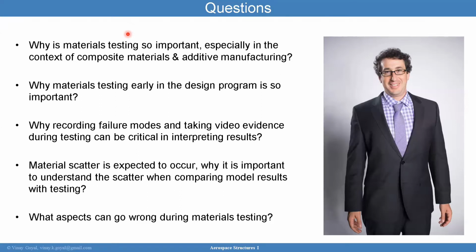Yeah, and I'll give you an example for that. We've seen this several times now with additive manufacturing. If you build large thin parts, you tend to get very anisotropic behavior, where your modulus can be 50% different in one direction versus the other. Not the strength, the actual modulus, the stiffness. And if you don't understand what you're making, your design is not going to be successful.